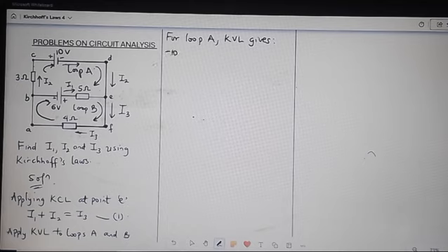We come to this resistor. You see that I1 is flowing through this 5 ohm resistor. It is moving in the opposite direction of this assigned direction we have chosen, this clockwise direction. The current coming through R1, that's the 5 ohm resistor, is moving in the opposite direction of this. So we'll have to take the potential drop here to be positive.